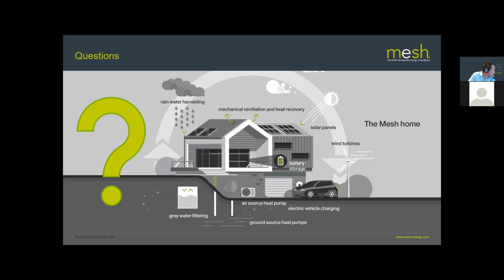Glyn has asked, are there air source heat pumps which work in a similar way to a combi boiler to be able to give you on-demand hot water if your hot water cylinder ran out? No, there aren't. And the reason for that is that a combi boiler will generally have a very high power output, so 35, 40 kilowatts, that kind of region. The physical size of an air source heat pump that can do that kind of output is pretty big. And you're typically only going to be putting that type of boiler into a relatively small building, so it just doesn't financially make any sense.